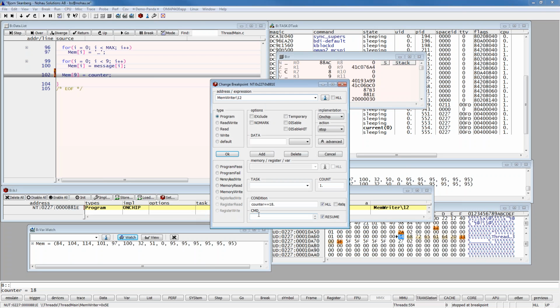And lastly, with the breakpoints, I'd like to say that you can also access the command line with the breakpoint. This is typical if you have a piece of code where you take care of errors. If you come to this piece of code, you can execute a Lauterbach script, which will do some saving of some variables, perhaps looking at some RAM or memory, or checking some status of something else.